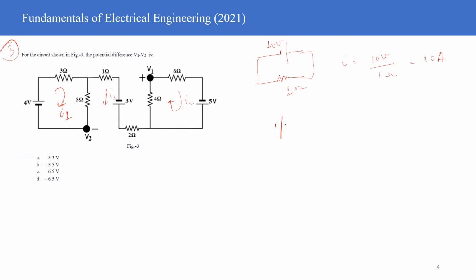See, if I have a voltage source and I connect it, in case 1 you have a 10 volt voltage source with you. You have the positive and the negative terminal. So any current which is exiting must find a way to the negative terminal, right? Somebody has responded, no, there is going to be no current in branch 3 because it is an open circuit. That's right. But let me just explain. Any current which is leaving the positive terminal must find a way back to the negative terminal. If that is not the case, then it is known as an open circuit, basically.